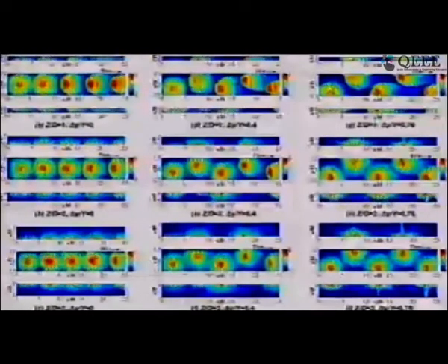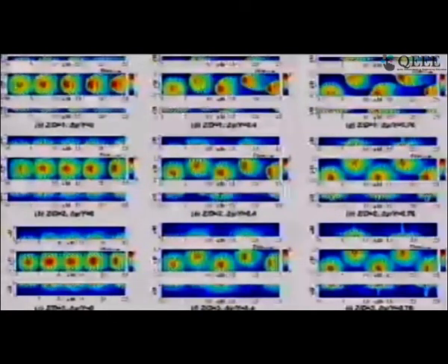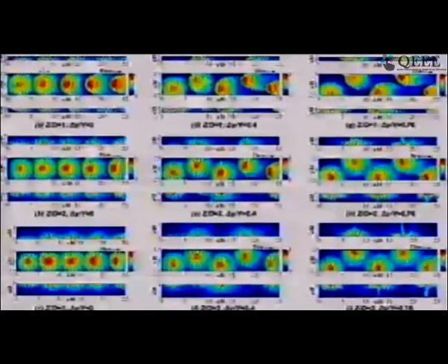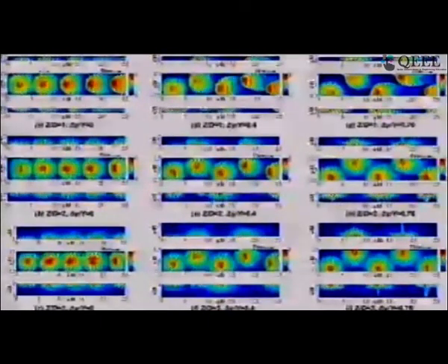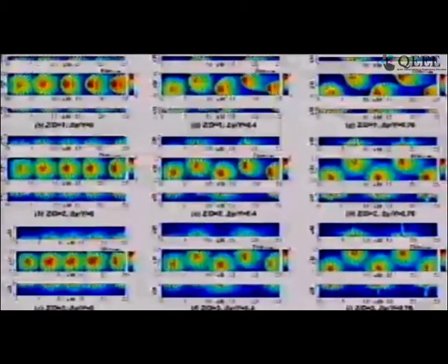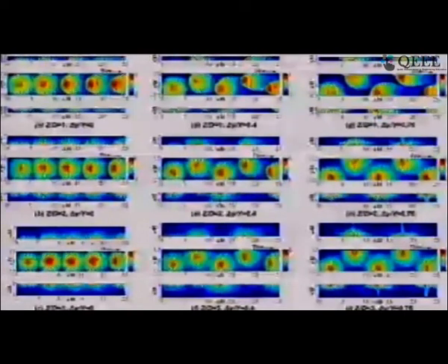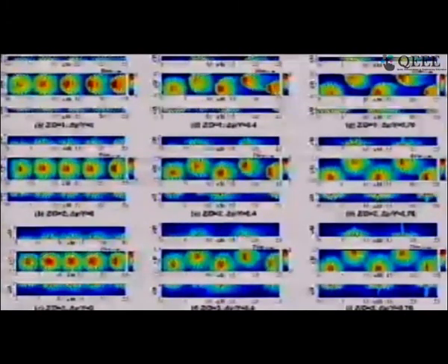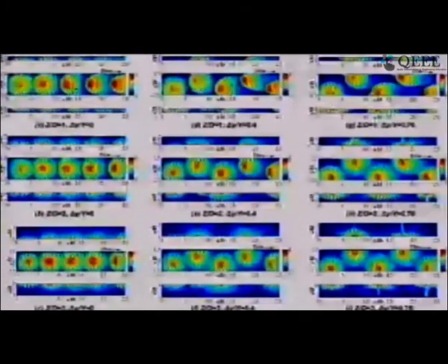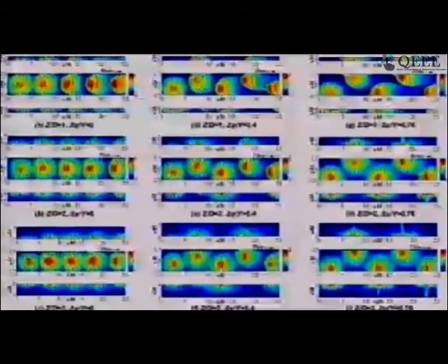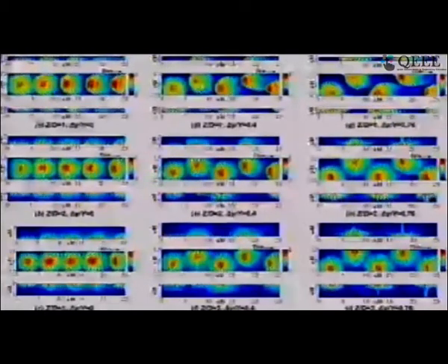A fairly high-end heat transfer problem, and what you see is all these small, nice, colorful pictures where they took a surface, drilled holes in it and put air through this, and they have coated the surface with the dye. Here you can see different ranges of color, and it tells you where the surface is hotter, where the surface is cooler, and from this you can also qualitatively figure out where the heat transfer coefficient is really high, where it is low, and how it distributes itself on the surface itself. So this is a very powerful way of getting information.